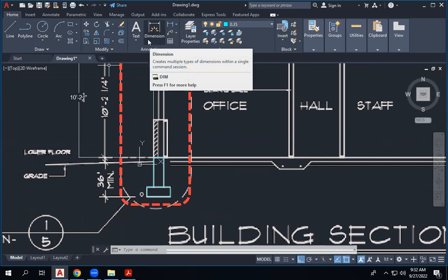We will try to change it, because if you have so many thick lines in between, because actually the line weight depends on where it cuts and also the material that we are using. If it's a brick wall or concrete, we will give a thicker line. And if it's a timber or any other material like tiles, we give a thinner line, even though it cuts. It's just a graphical interpretation of how the drawing should look. It should look better rather than having so many thick lines, then it will not show very nicely.